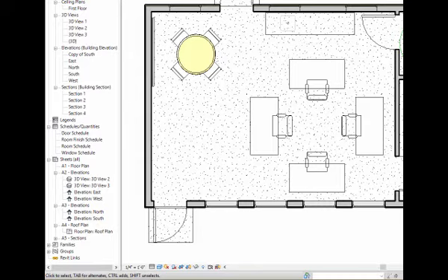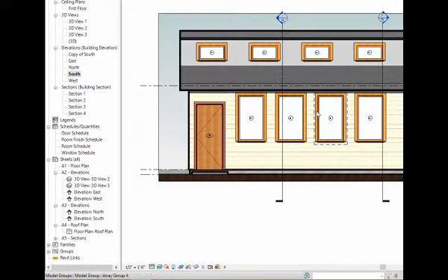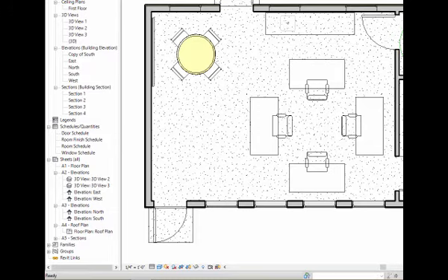So what I want to first reinforce about the plan view is that we have these different plan views for the first floor and the roof plan. We have those because there's always one plan view for each of the views, for the roof level, and for the first floor level, we have a plan view set up for those. Now, what happens very quickly is we often start having so much information that you really don't want to show it all on a single plan.